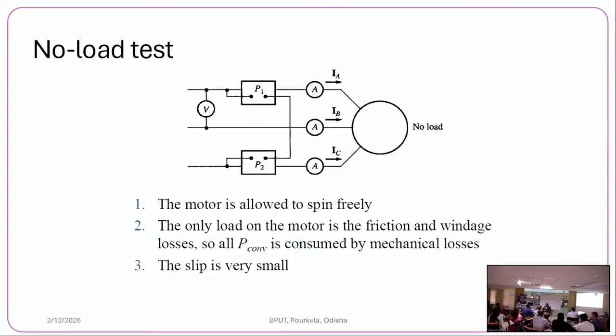Suppose this is a current. If you apply direct current, the current will be uniformly distributed along the cross section. So you take the total cross-sectional area to find the resistance of the conductor. When you apply AC, because of higher frequency the reactance increases, so current does not flow in the center.